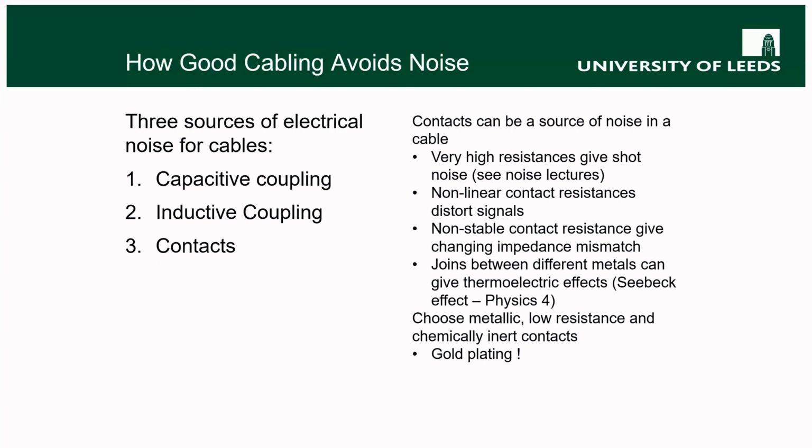And this is why high-quality cables are gold-plated. If, however, your signals are large digital voltages, then gold plating is a bit of a waste of time. So if you're buying gold-plated digital cables, someone's trying to pull a fast one on you, but buying gold-plated analog cables might actually be a useful thing to be doing.